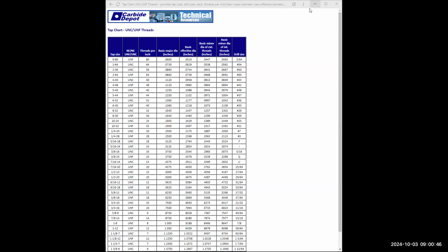All right, the next two holes are a little trickier, but I want to do this end one first because it's kind of the same. I want to do the end hole first. All right, so it goes down a depth of a quarter. So type in offset, enter, type in 0.25, enter, click on this line and indicate downward. Click, enter. I hope you're keeping up with me.